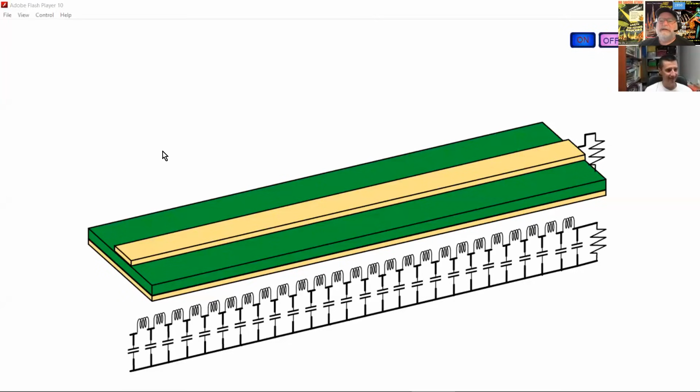Okay. So here is a simple transmission line, a microstrip transmission line, and can you see that on your screen? Yes, I can. Okay. We're going to launch a signal at the beginning here. It's just going to be a little voltage source, a little step voltage. It's got some source impedance, 50 ohms or something. And we're going to increase the voltage between the signal and the return path over here at the beginning. The first principle of signal integrity is all interconnects are transmission lines. I happen to draw this one as a microstrip, nice and uniform, but it's any signal and the return path.